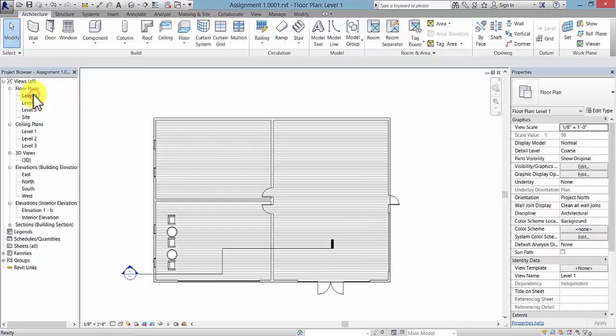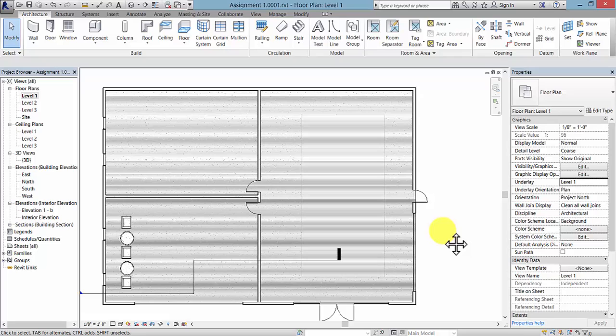Let's go to level 1 and then use underlay over here in properties to see here level 2. By changing the underlay to level 1 and picking apply, we can see the floor above and place a stair. For our rendering, we can just go ahead.